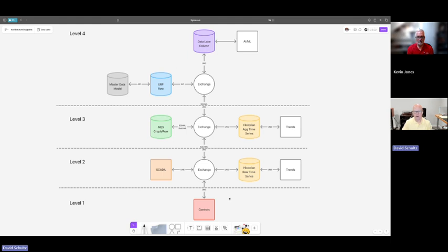Going back to this concept of a unified namespace, what we've done is we've added intelligence as we've integrated this information, starting with just basic asset models that are controls. We've now added some higher level details at the SCADA level. We've also introduced things coming from our manufacturing execution system and or our ERP. So we've added that context of not only our time domain type information, that SCADA data, telemetry information. We also know what product code am I running? What's this work order or production order from the ERP? Who's doing this type of work? Along with all the other information that's there.